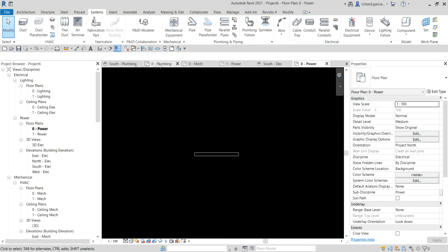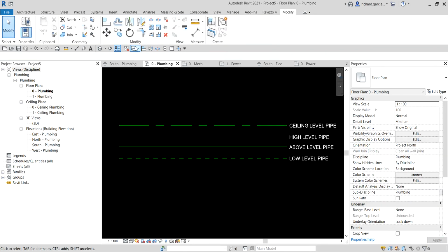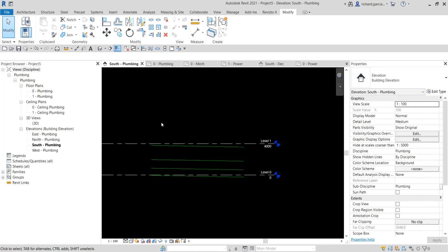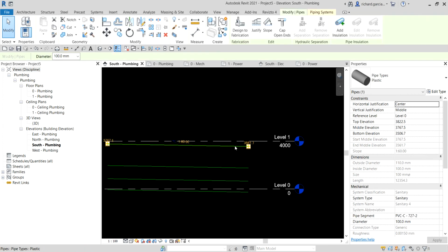The difference between the pipe, if you are going to use the invert elevation, the invert elevation always references to 0. So if you create another pipe here, it always references to the 0. Do not think that if you draw your pipe here, you can see the invert elevation here is, where's the invert elevation?